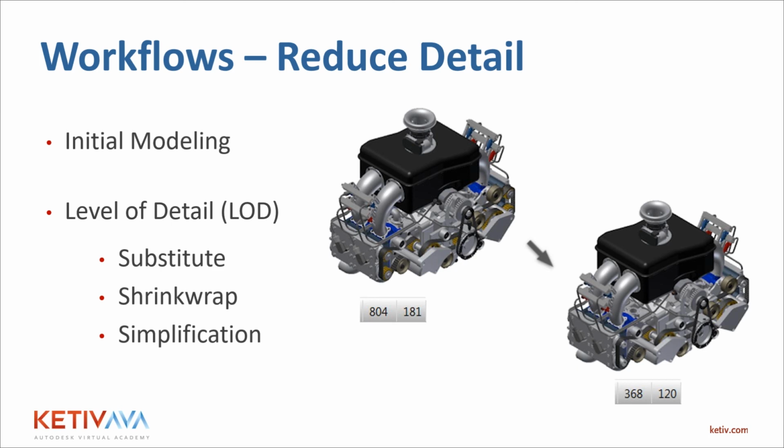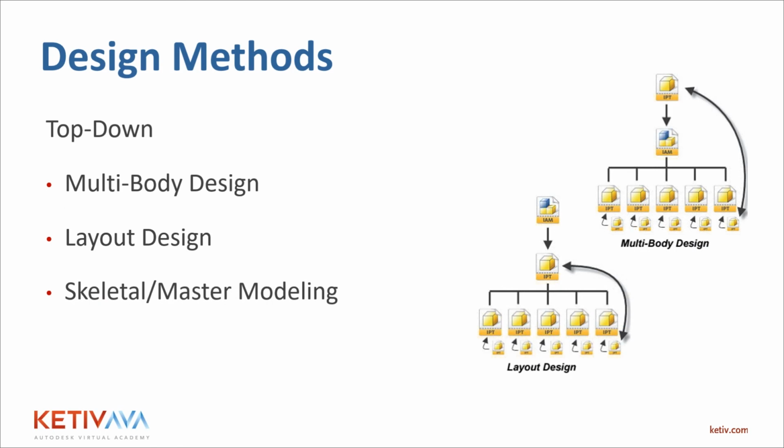Okay. The last thing I want to talk about in terms of large assemblies is maybe more fundamentally changing the way you design things. And we certainly don't have enough time to get into this today, but there's ways to create your models without constraints, to basically constrain them at 0 and model them a certain distance away from 0, so that when you assemble your drawings, you're not working with constraints. Every time you open up an assembly, it checks the constraints, updates the constraints to see if they still work, if parts still fit. If you simply ground things at 0 without any constraints, they open up much faster.